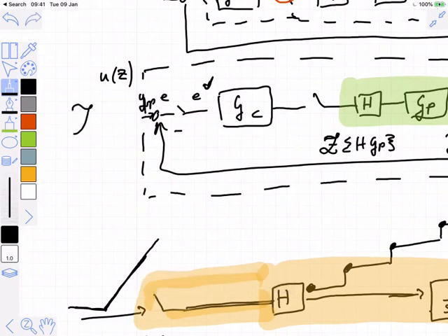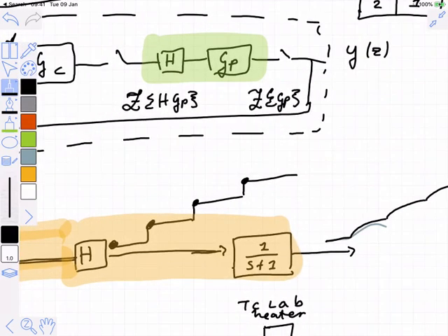So in other words, if I have the Z transform of Y, or let's say Y is P of T, I can kind of call that YSP of Z. And recall that I like writing this hold element in there to distinguish between taking a Z transform which contains only the GP itself and taking a Z transform that takes both the hold element and GP into account.